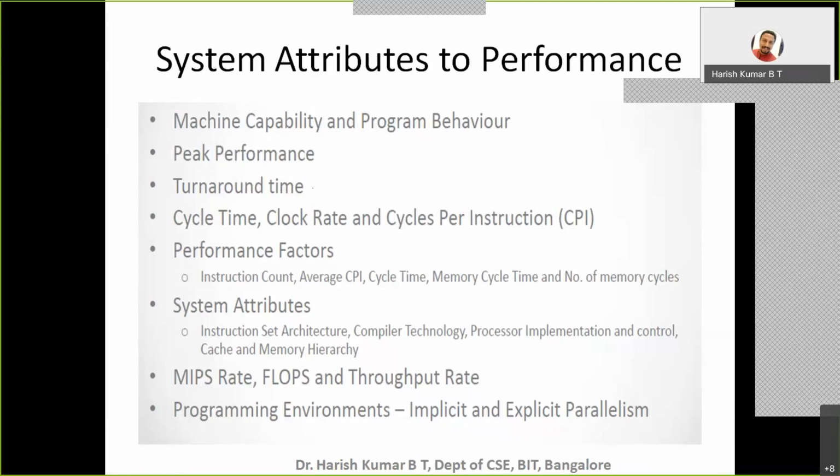Now, how does the processor get the clock cycles? Clock cycles are supplied to the processor from an external circuit called the oscillator circuit. It is a separate circuit, and it supplies all the clocking requirements of the processor. In that oscillator circuit, there is a quartz crystal. If you have observed printed circuit boards with a small microcontroller, you might have seen the quartz crystal. On top of it the frequency is written: a 12 megahertz quartz crystal, or 16 megahertz, or 64 megahertz, something like this.